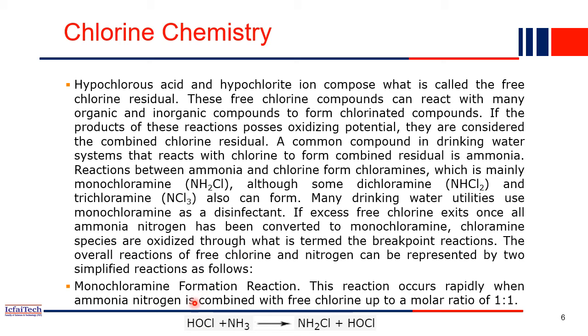This is the reaction you can see: HOCl, which was formed in the last slide, will react with the ammonia present in the water, and NH2Cl, the monochloramine, will form. This is the agent responsible for the disinfection properties of water.